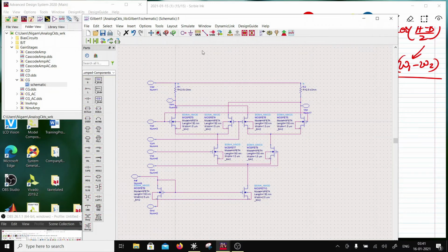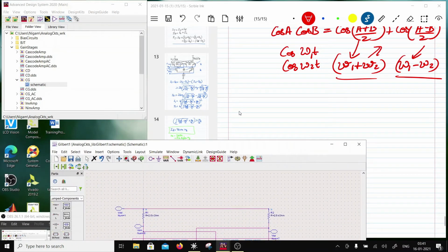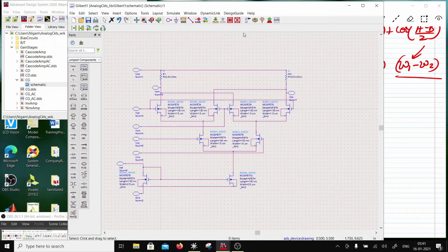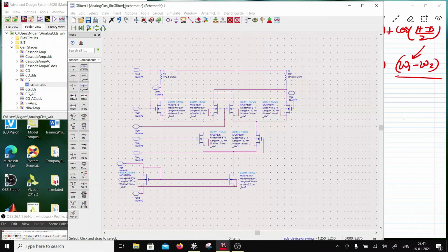Now you can design it elaborately because you know what is the conversion gain. So you can design for a given conversion gain. But another thing is that the conversion gain trades off with the input voltage range. The input voltage range is basically going to be twice of root 2 times of V overdrive. So if you take the conversion gain up by GM or mu n CX by 2W or by K, right?